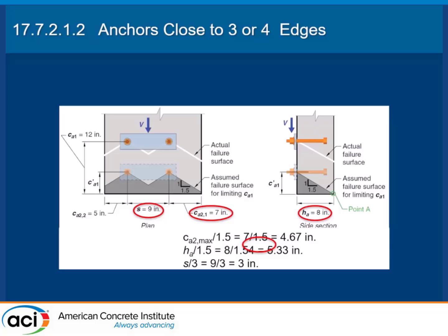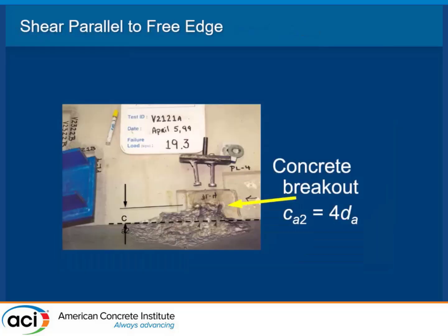That's all well explained in the code, but it is a key concept, because if you look at this and say, well, I'm just going to move it back further, you're really not going to get any more. You might have to start thinking about putting some hairpins in. I used to do tilt wall design as well, and I use hairpins all the time to start dragging my load away from edges. Just common sense.